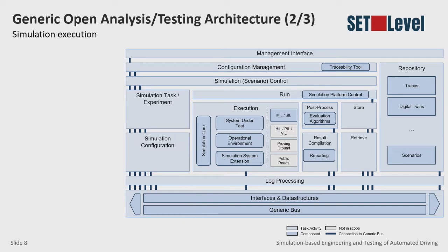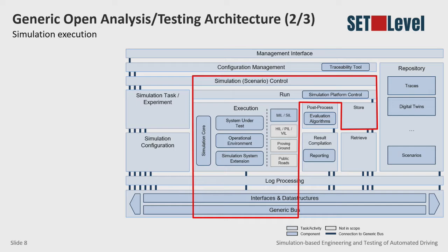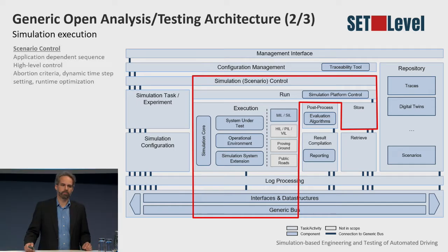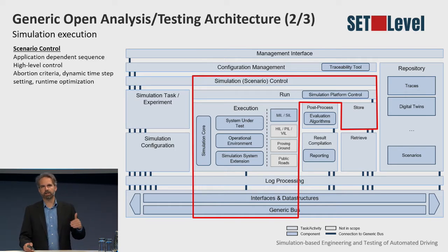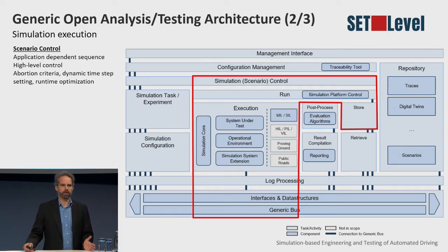For the execution of the simulation, we have the element of the scenario control as a top-level component, which controls the execution of the simulation and includes things like abortion criteria or setting time steps, which might be dynamically varied within different simulation runs.